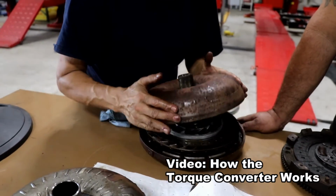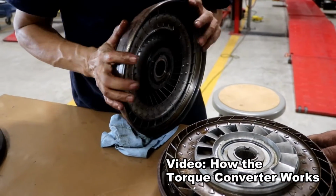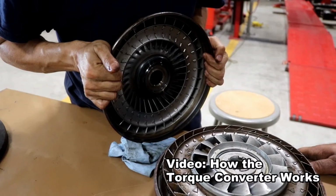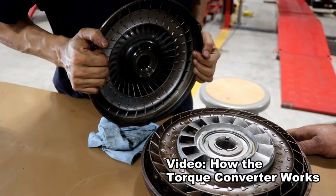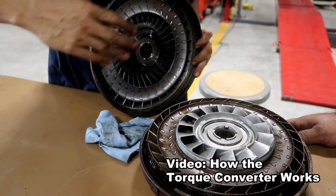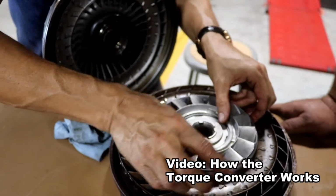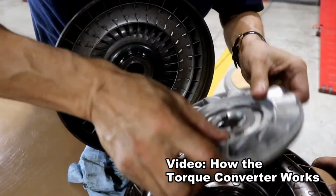Now I am going to disassemble it, and we have two turbines. One turbine is welded on the housing. Look at this. This is welded. The material is a special titanium steel, the same quality as the turbo in aviation. It's a turbine with the blades in one direction. And look, the oil enters here, and this element is the stator, this element helps to introduce the oil onto the blades. Right now I am going to explain.